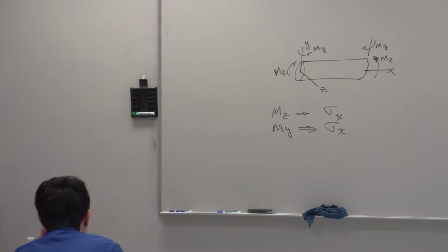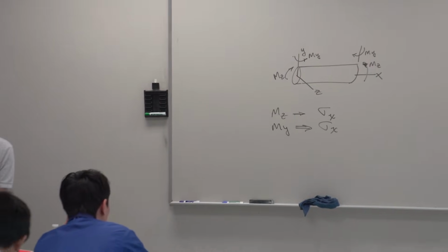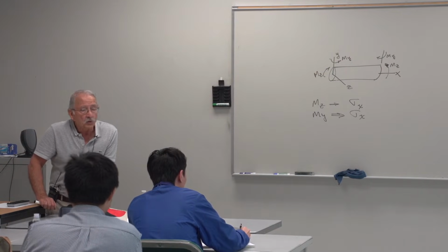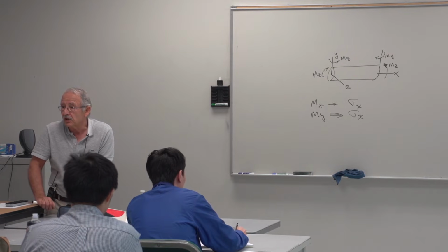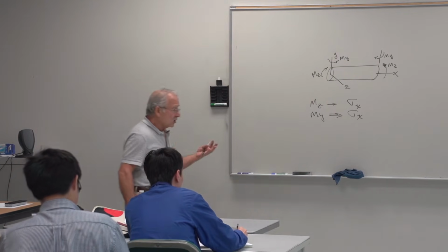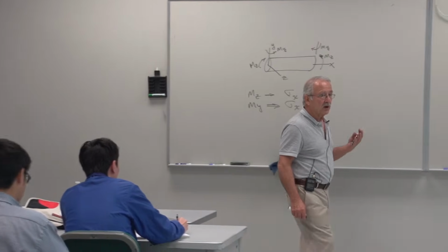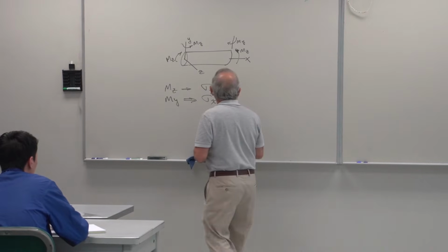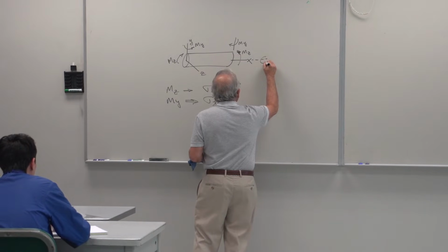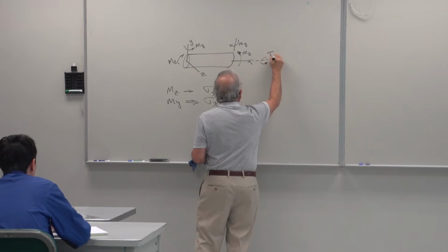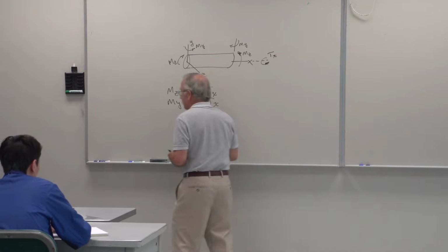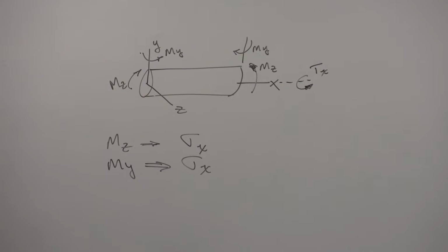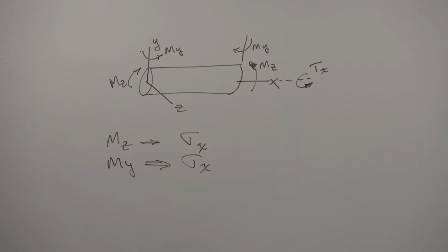There will be no normal stresses in the y or z directions, regardless. The axial load that may be applied will also give you a normal stress in the x direction in this case. So don't come up with a sigma y or a sigma z or something like that in problems involving shafts. Of course, if you apply a torque in the x direction, it will create a shear stress in the shaft.